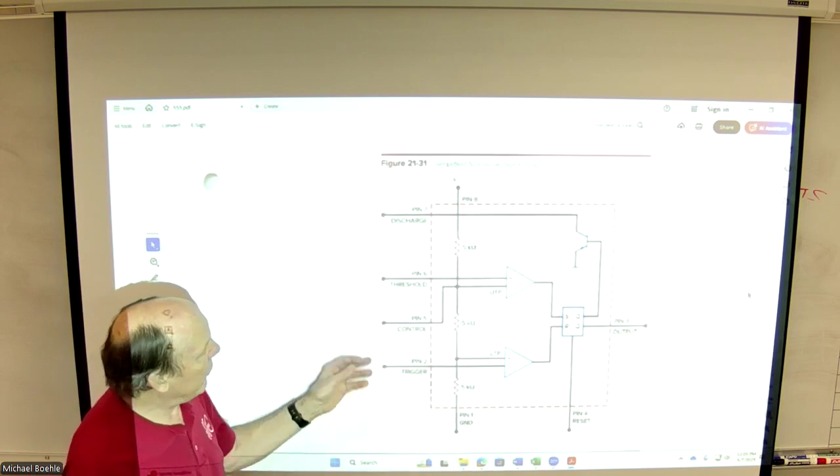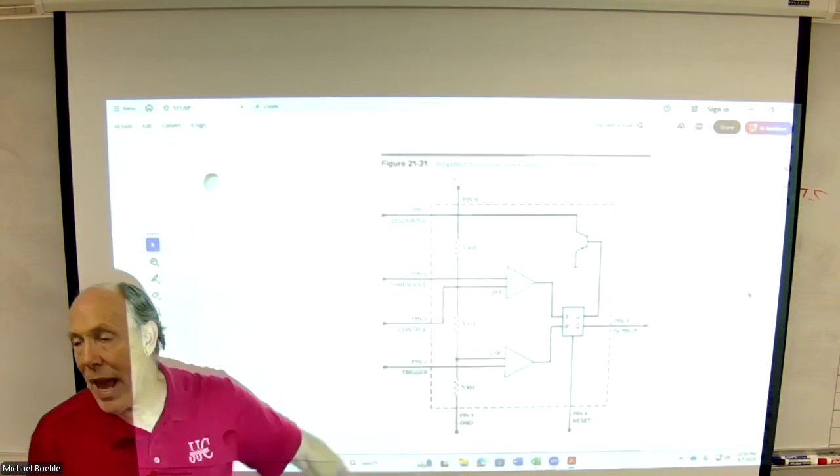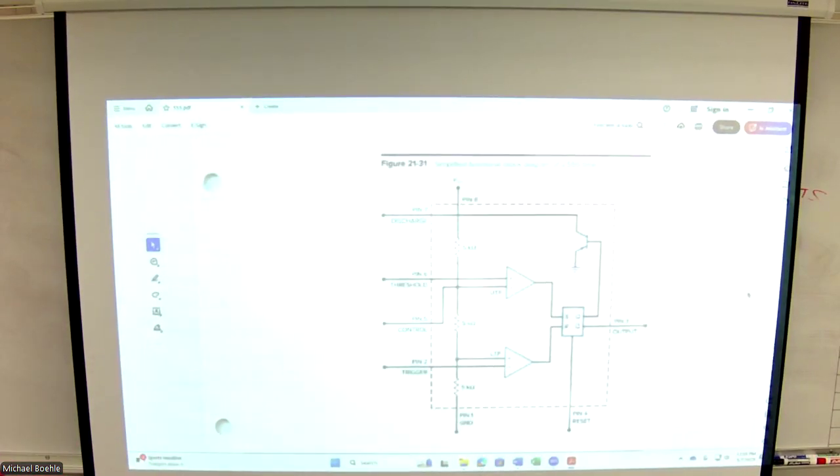Typically, the way that is done is I use pin 2 as a trigger, and then the output will change on that trigger for a set period of time and then go back. So I can basically create a certain width of a pulse using that trigger. It's only one stable operation. It stays in that stable operation until I trigger it. It gets unstable. In other words, it changes for a set period of time, goes back.